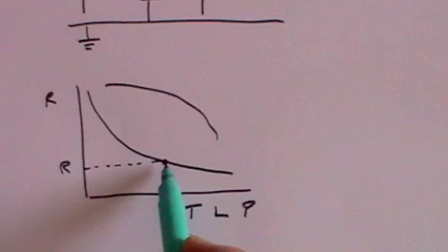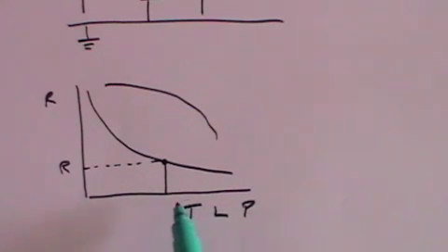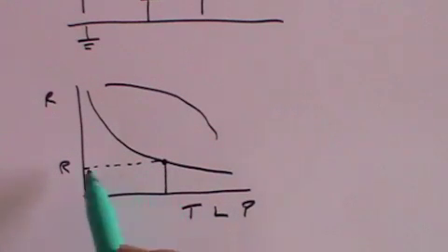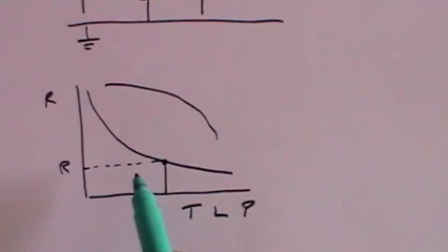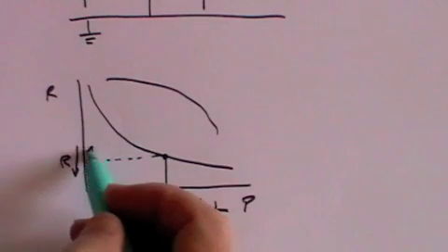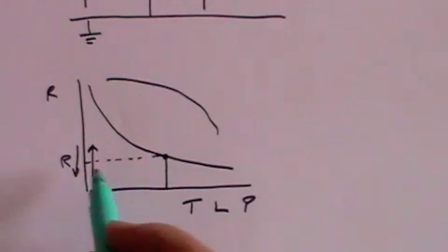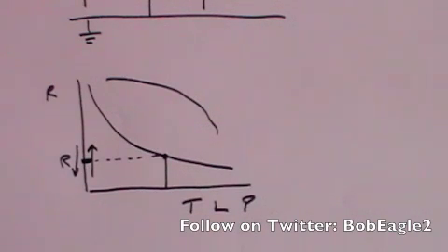You'll actually have to work out at what point you get a particular resistance that coincides with the critical temperature or lighting conditions or pressure, where you want the resistance to go through the key point. And then you have to set up your circuit such that as the resistance passes this point one way or the other, when it gets to that point, the effect is that the operational amplifier's output flips from being positive to negative or vice versa.